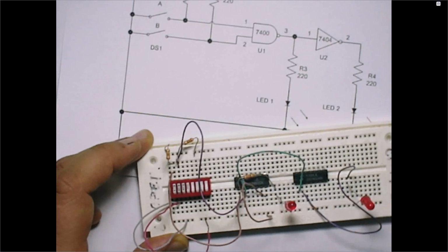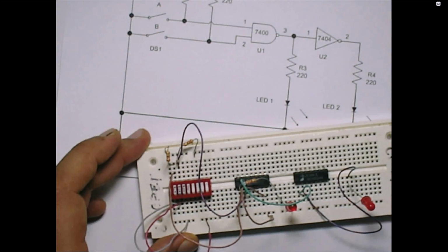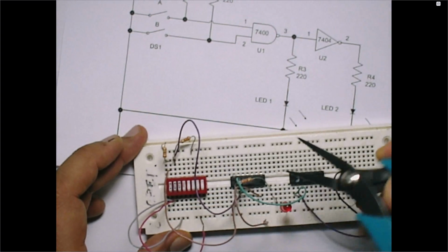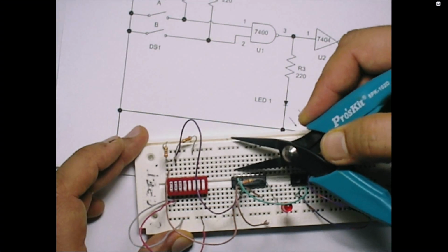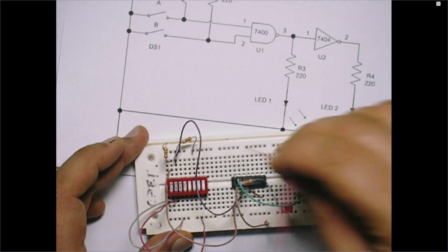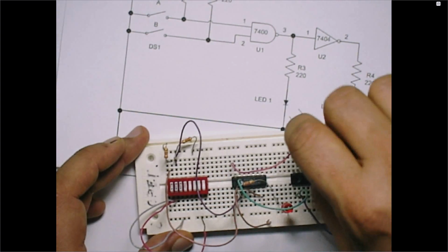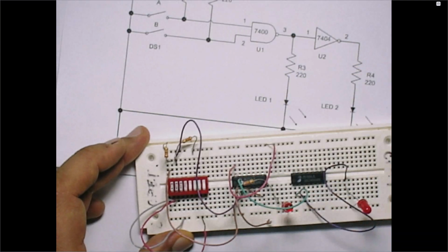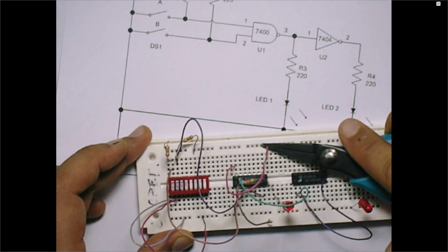And then pin 14 has to be VCC, right? Which one is pin 14? I started counting from the bottom, went all the way up to 7 at the bottom, then 8, 9, 10, all the way up to here is 14, the last pin. That's my 14. So I'm connecting the 14 here. I connected the 14 to the VCC, so that means any point at the top. I can choose any point from the top row and use my needle nose plier to connect it.